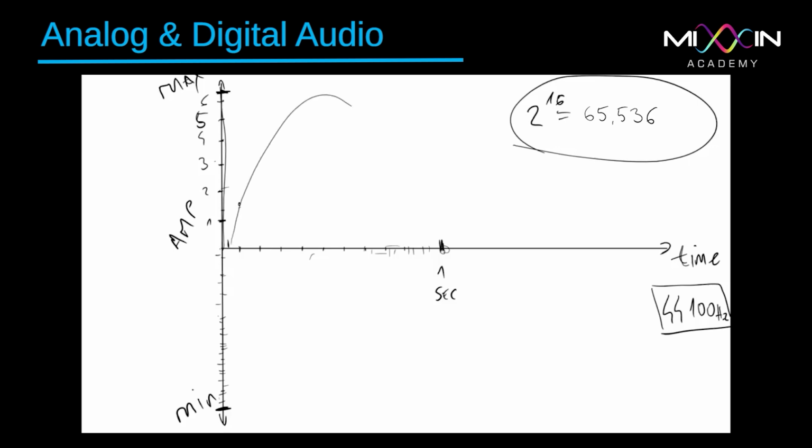So the problems I talked to you about with having low resolution really don't transcribe even to the most standard and most common commercially used digital product we have had for years already. Just imagine when the CD came out, and that was a long time ago, we already had that resolution. So 16-bit, this is how we call that, 16-bit, 2 to the power of 16 divisions here, and 44,100 divisions each second. That's really a lot.